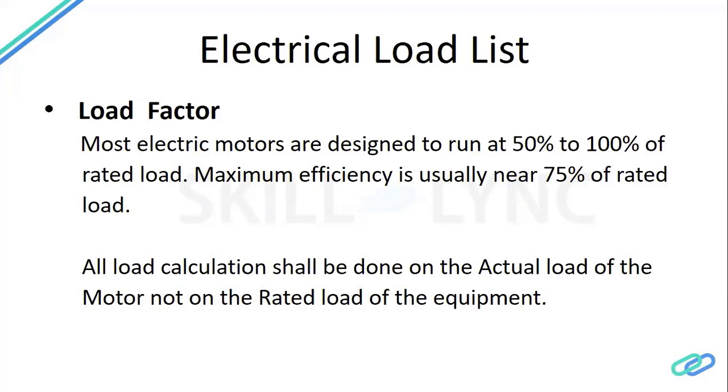So what you will do is calculate the load factor. What is the load factor for this motor? You apply the load factor in the load list, and accordingly you calculate the power required by the motor. That's why all load calculations shall be done on the actual load of the motor, not on the rated load of the equipment. This we do to prevent oversizing of the transformer.